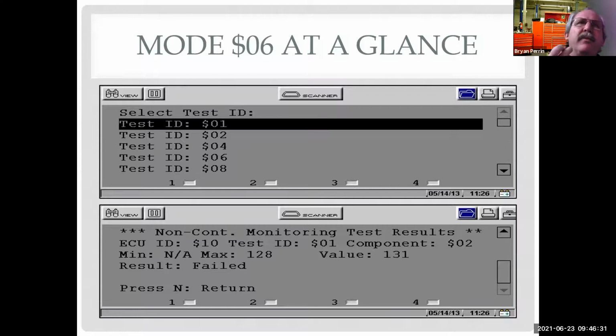Okay, so anytime the check engine light comes on, there's a problem. Keep in mind, many of these are 2-trip codes. So what we really want to do is put that problem into perspective. Even when that comes in, I'm still doing direct testing on it. But if it tests okay, or if it tests marginal, which is a lot of the case, it tests in that weak area, it's not great, but it's not horrible. Well, do we really want to replace it just because it's not great?